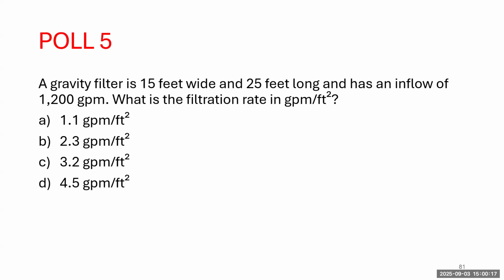We'll talk about turbidity measurement in a moment, but initiating the filter at the right time, being aware of that initial spike in turbidity, and then ending the filter run at the right time, and having the right rate of backwash will help the filter run at its optimal level and help you to at least achieve that compliance goal and maybe even optimize goals. We'll talk about some optimized goals in a moment here.